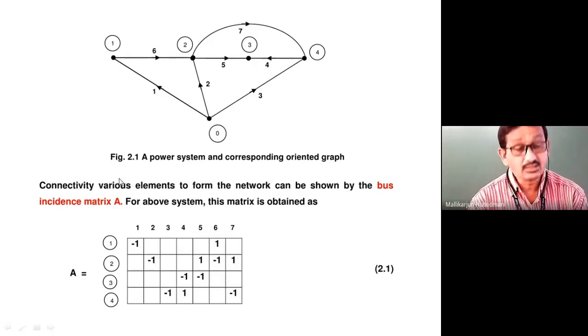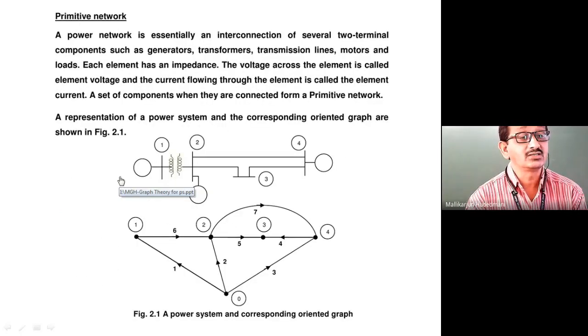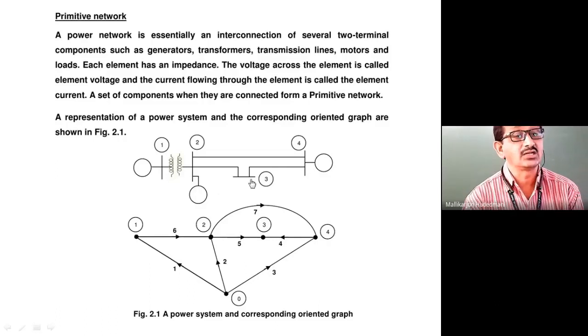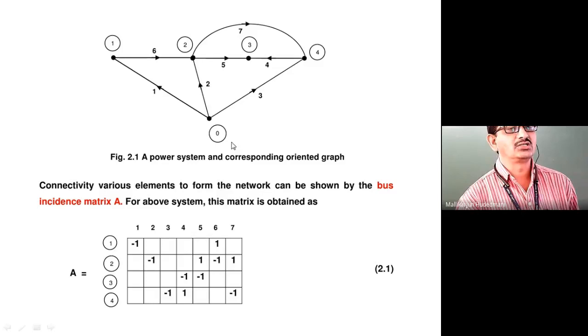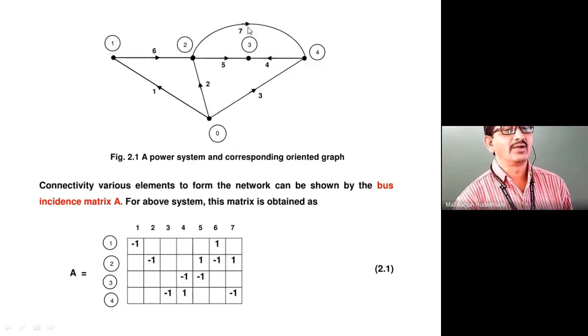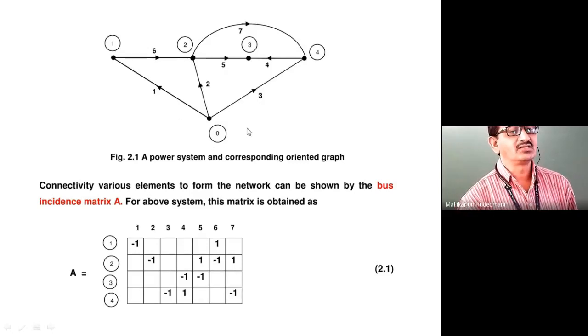So this was the problem we began, and I took you through how the A matrix is obtained for a given network by topology, and I am coming back to this electrical single line diagram, how a graph is represented, how usually orientations are given. If orientations are given like this, how to represent the interconnection in the form of a matrix, I wanted to convey to you. Suppose this problem was considered as a reference, so many elements, 7 in number, I have, so many buses, physically 5, but the reference is taken out, hence it becomes a 4 cross 7 representation on this slide.